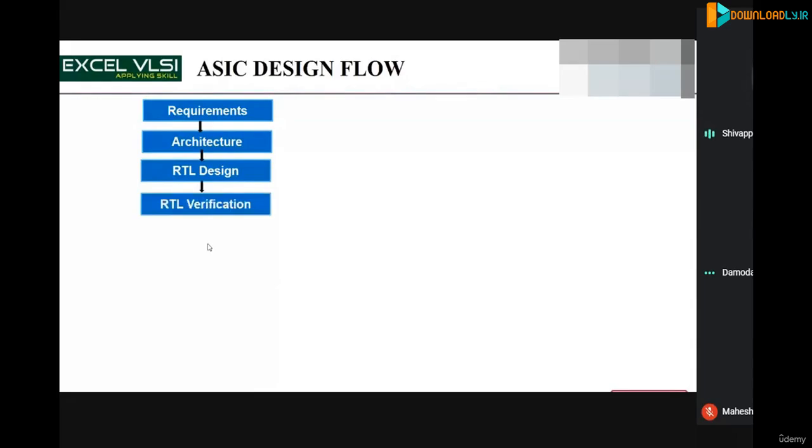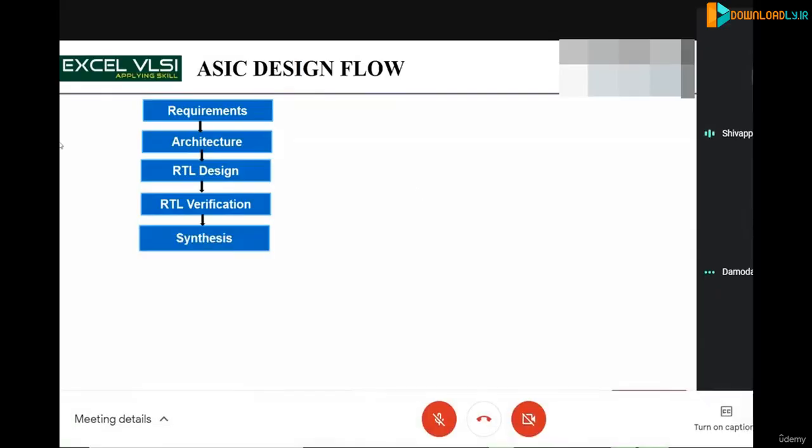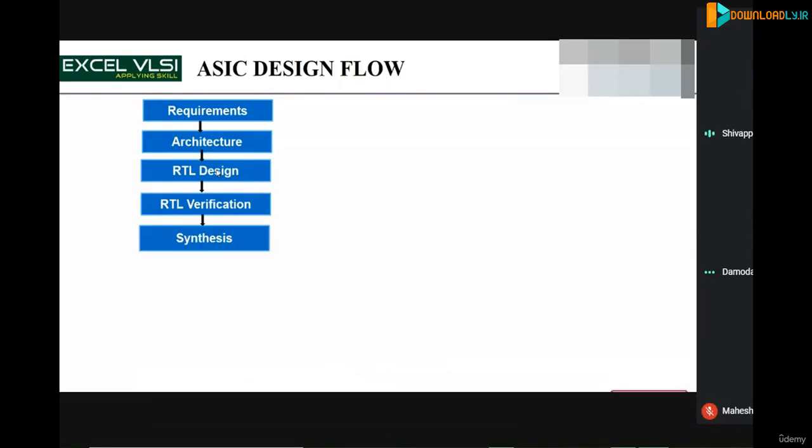And RTL verification. Now you have to verify the functionality. I will touch upon all these topics separately, even these blocks, in upcoming slides. So I'm just explaining the flow: design, verification. Now, once the design is done, you take it to the synthesis process, which we'll explain more. Okay, and this is logic equivalence check.